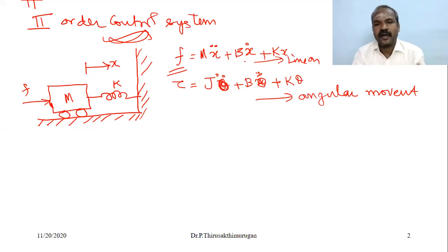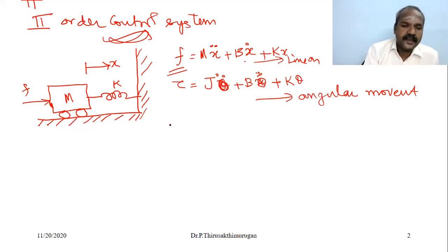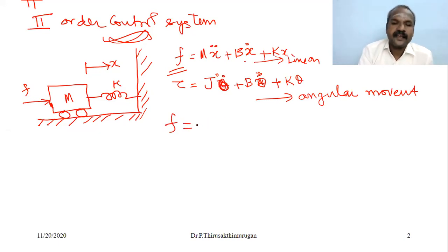What is the feedback to the control law? That is the sensors, the sensed feedback. What is the sensed feedback? F equal to minus Kp times x minus Kv times x dot. So it is a proportional gain times the displacement minus a gain times the velocity.